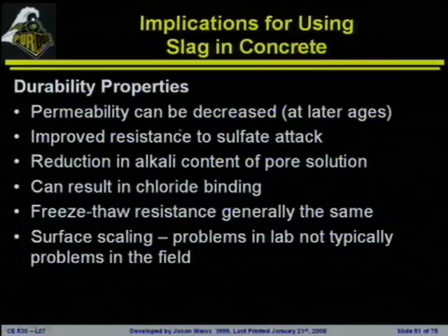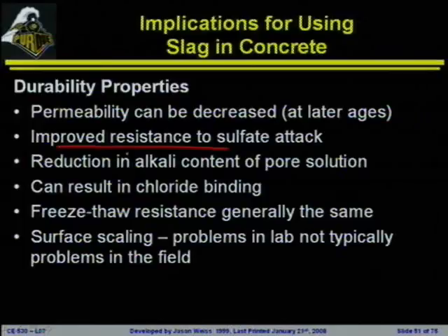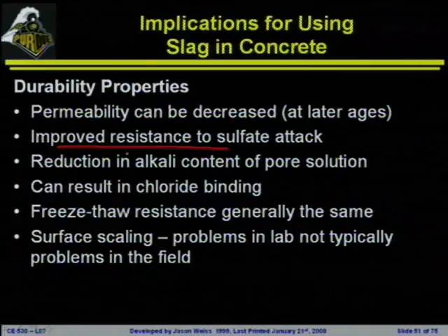Durability, a lot of times you can see the permeability decreasing because this material will react more slowly over time. We're filling in more of the pore space. You'll also see improved resistance to sulfate attack and alkali silica reactivity, and this is mainly because we're going to have a reduction in the alkalis in the system, and we're going to change the permeability of the system. We're going to densify the overall system.